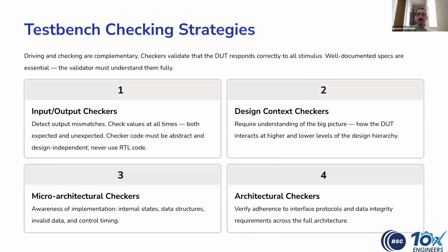Design context checkers understand the big picture interactions. We need to understand how each of the blocks interact with each other and with other checkers. For microarchitectural checkers, we should be aware of the implementation of the design. We can check internal states, data structures, invalid data detection, or fine control timing scenarios.